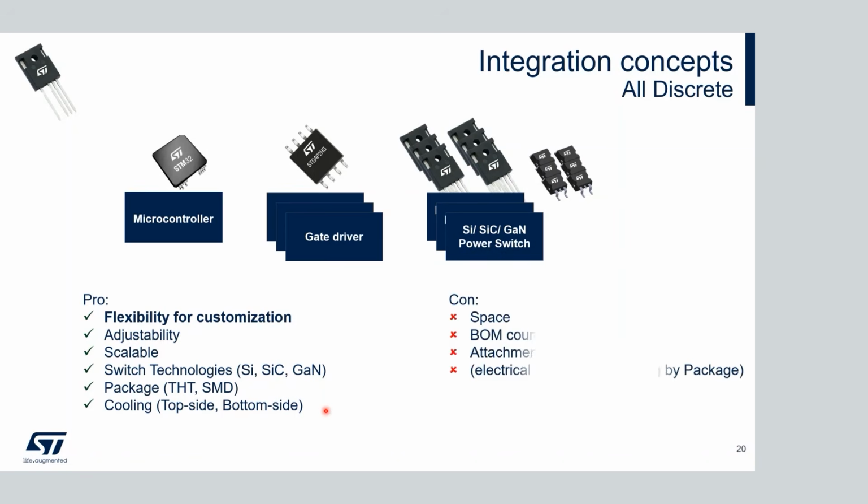But there's always a but. It needs more space, because you have the space around the device, the circuitry around, the gate driver around. So you have many components to place. And there's the way the heatsink has to be attached, either if it is just the PCB acting as the heatsink, maybe you want to attach also a heatsink to that. In some applications, this is also needed, or you have the heatsink on the top. But the main con here is the electrical insulation, because most of these packages have no electrical insulation.